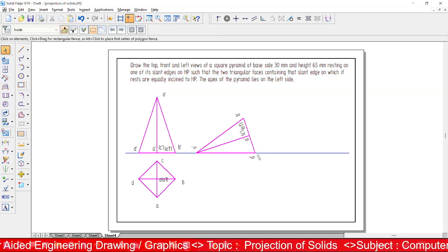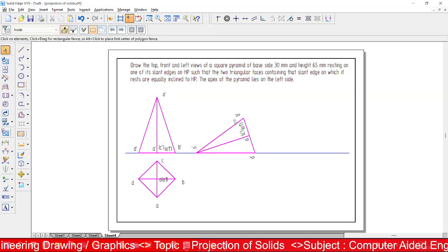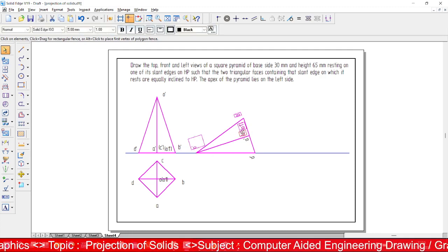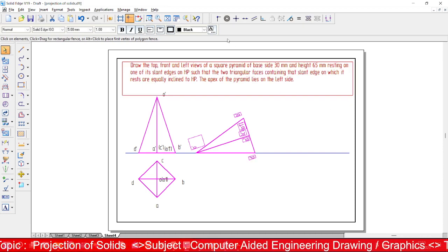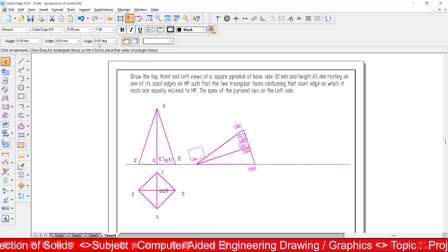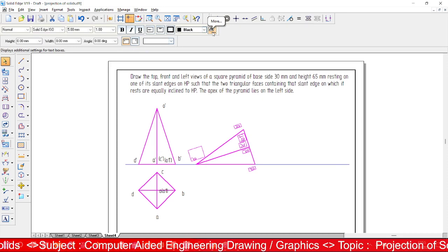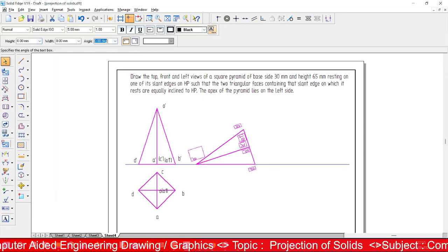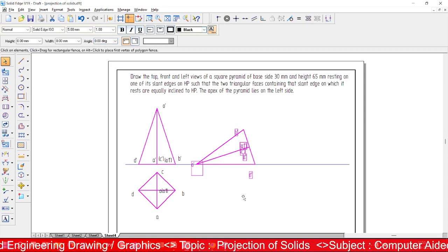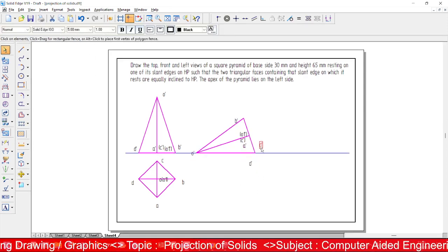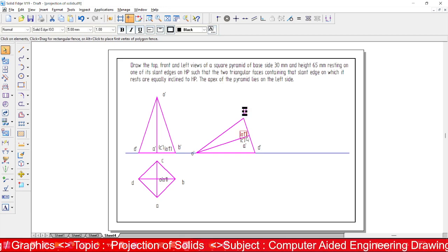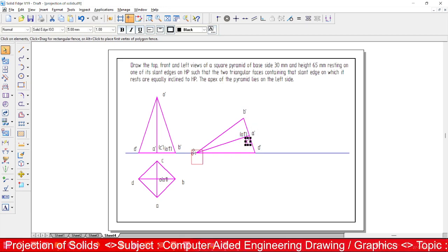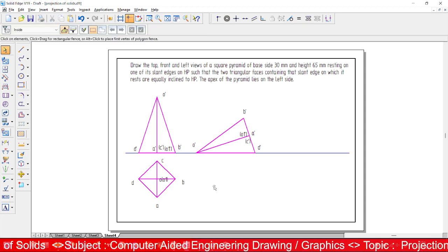Now for changing the orientation of these fonts, select all the points with the control key or shift key, then go for properties. Then you can change the angle to 0 degrees. Some text is displaced because of the larger text box placement.